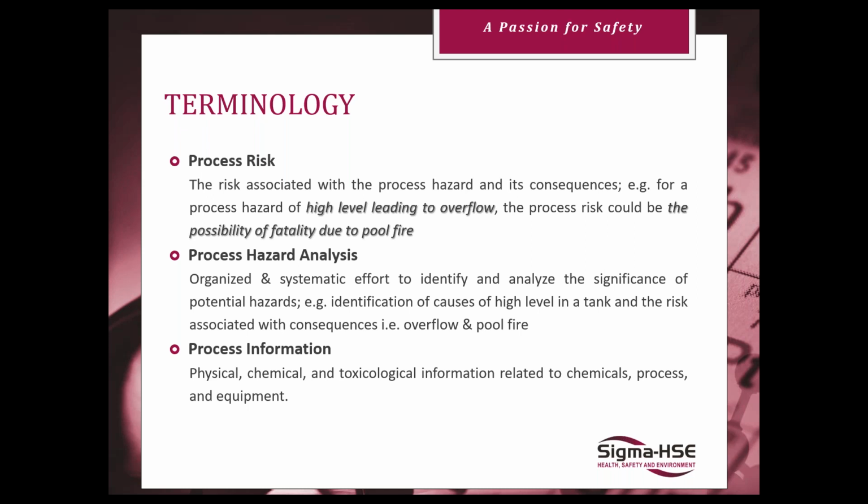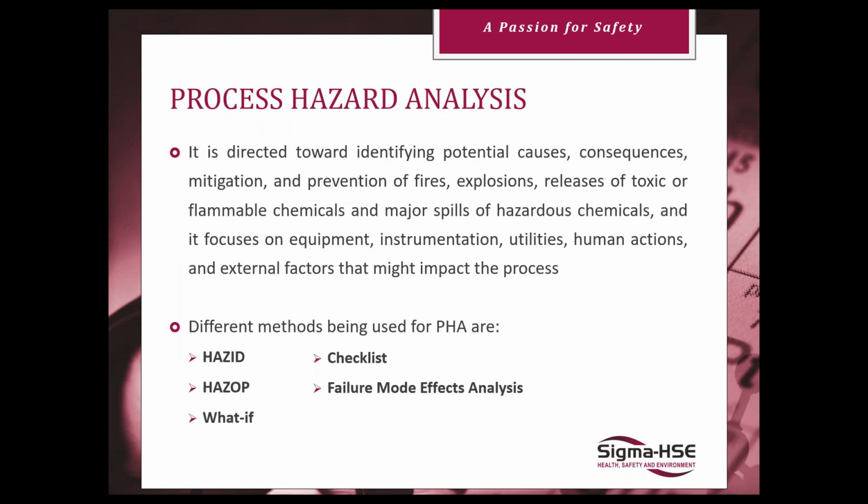And then process information: physical, chemical, and toxicological information related to your chemicals, process, and equipment, P&IDs, process flow diagrams, energy balances, your equipment information, you know, what is its max allowable working pressure? All that falls into your process information.